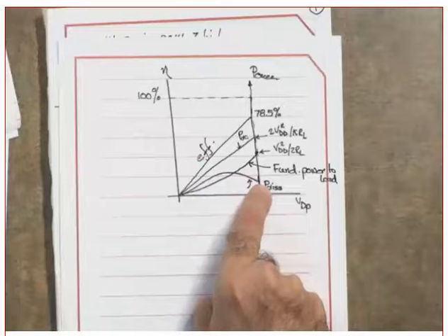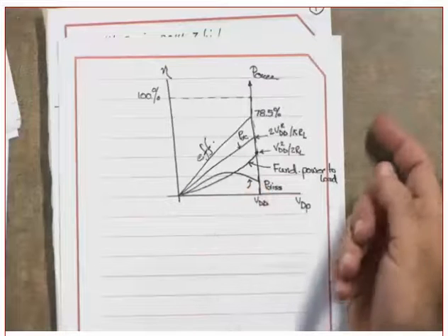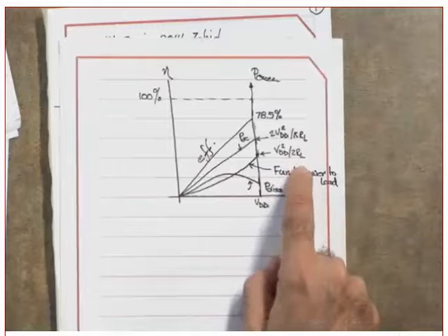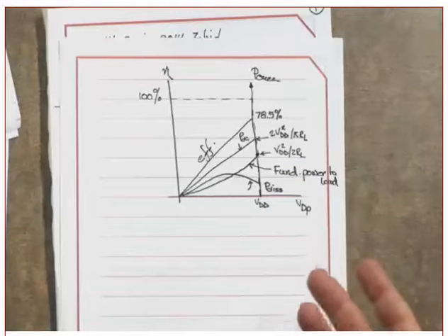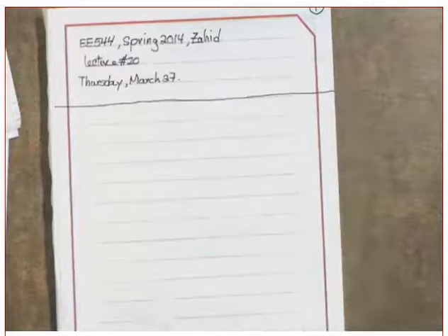That's the power dissipated. Power dissipated, remember, is equal to what? It's equal to the DC power minus the power delivered to the load. Clear? How come this one, all of it is divided by RL? Because that is the load. Are you following me or not? The power delivered to the load is what? Is the voltage square divided by what? Divided by RL. Clear? Okay.